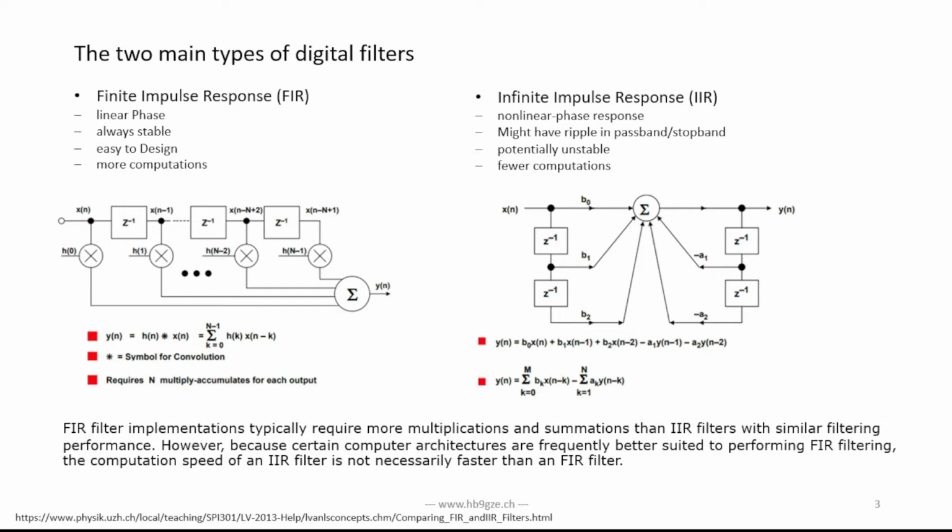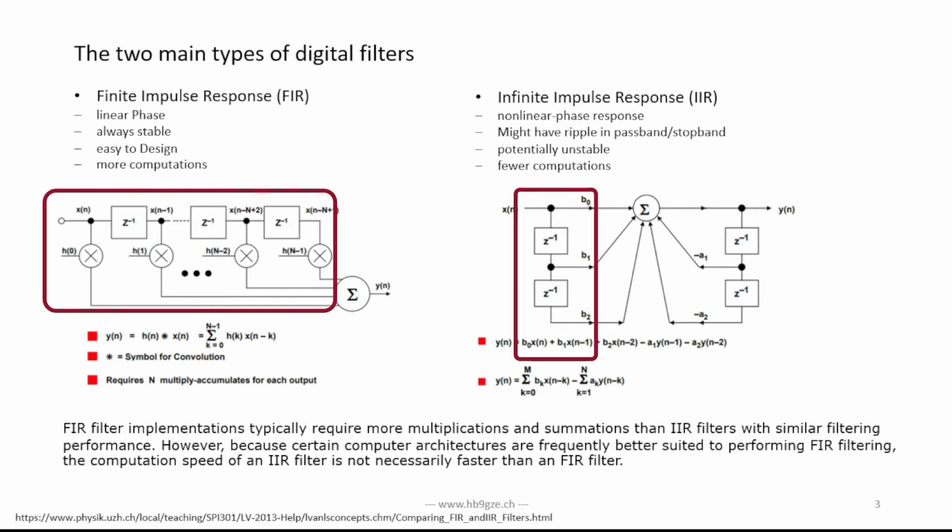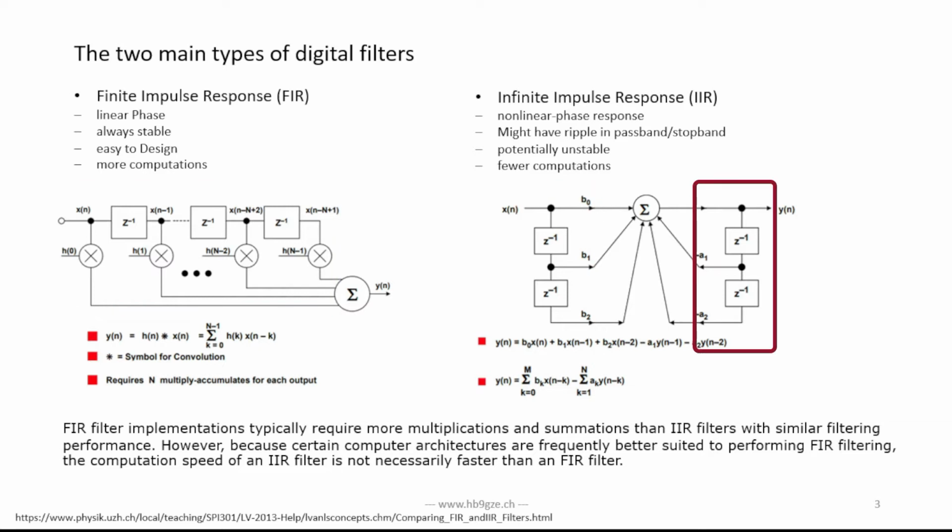And that's because you don't only use the input. If you look at the input side, the calculation is exactly like an FIR filter, but you also have a computation of the output, the history of the output fed back into the summation of the filter. And therefore, if you have an input and you drop the input back to 0, you always feed back a little bit of the last output. And even if that's getting really small and really small and really small, you never get to 0.